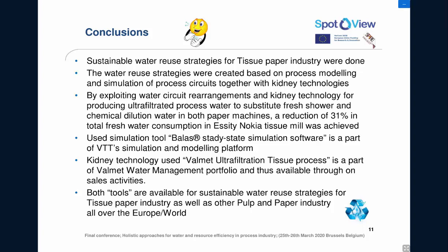And if you calculate, if you take this kind of process water, which is already at the right temperature, about 40 to 45 degrees Celsius, and in general the tap water or other water you take to the process is about 25 degrees, then you don't have to increase the temperature by those 25 degrees. So the heating amount is 25 degrees. Then the savings can be about 200 kilo euros, so 200,000 euros per year in heating value. So this is quite a lot.